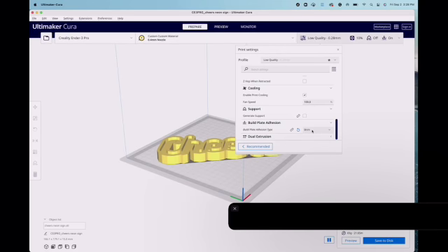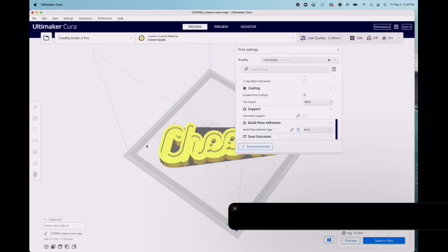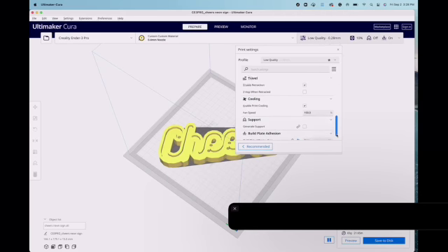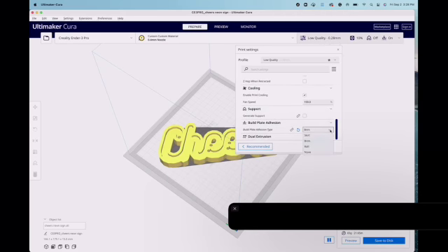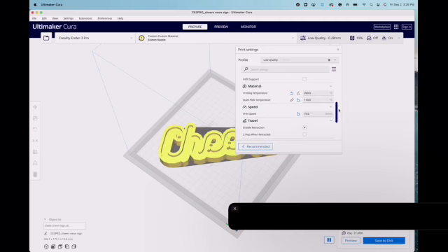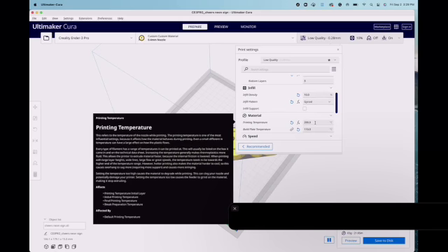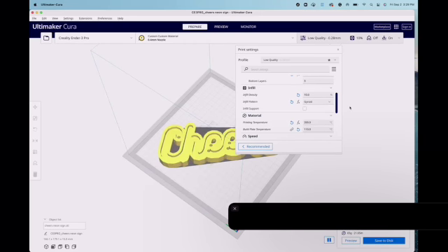And so I like to do a brim. Brim is like, think of a hat. The hat has a brim, right? So when you do a brim print, it creates a brim around your text before it prints it. And I like doing that. The other thing you can do is go in here and look at your settings. Whatever settings you set here, you're just playing around with your printer settings, but this doesn't save and set your printer for you. You have to go in later and set this for your printer personally.